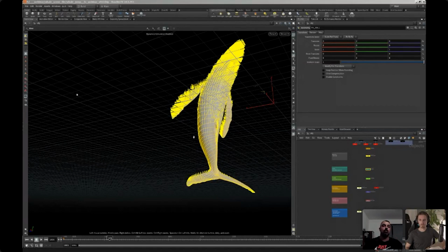I try to go with a small tank and then just scale it properly if I need more. Or if I'm testing, for example, a whale rising from the water and I'm just testing the head effect, I scale my container for the wedges just around the head. Why simulate 50 meters, just wasting time just to see the head? Yes. So scale the container and instead of 5 hours, it's 1 hour per wedge. And then later on, scale it back up to run the higher-resolution scene.